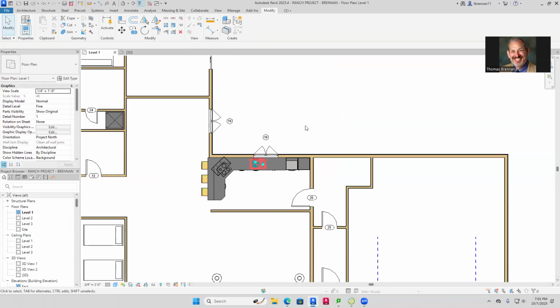So what does it mean by unconnected thing? Remember that. That means the default height is 10 feet. So your top constraint is just going right up to level 2 and stopping, just because it was at 8 feet, in the window. Right, so you put it up to 10 feet and that's fine. Okay, so what you would do here, a couple things.